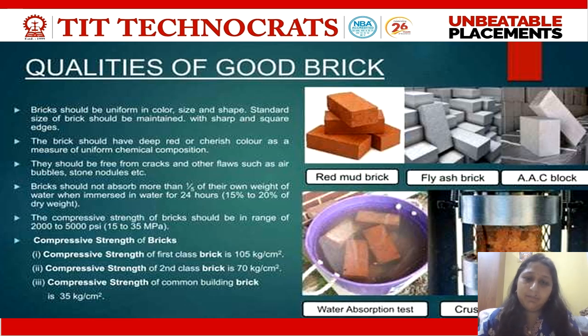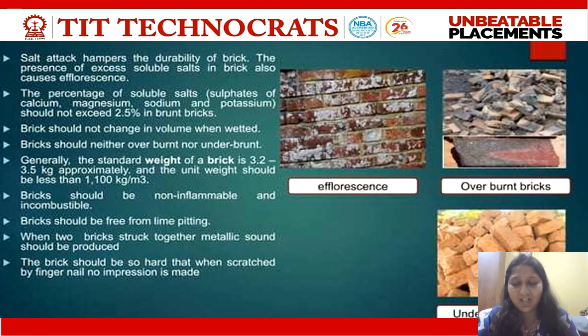Whenever I scratch the brick with my fingernails, there should be no marks present on the brick after scratching, which would show that the brick is sufficiently hard. When I drop the brick from a height of 1 meter, it should not break into pieces. If so, it means the brick is of good strength. If it breaks down, it means it does not have sufficient strength.